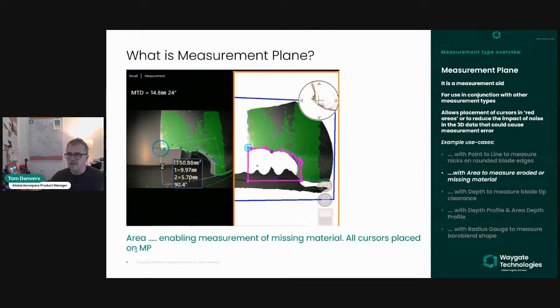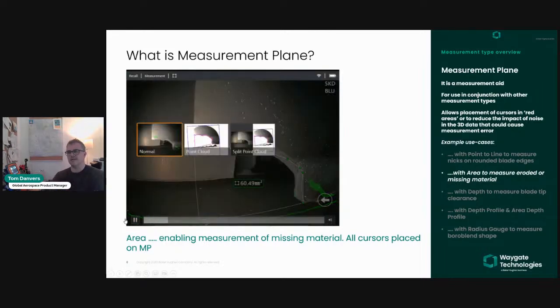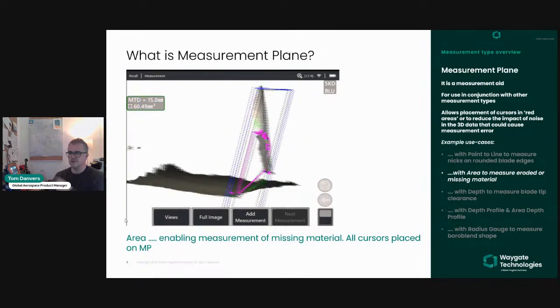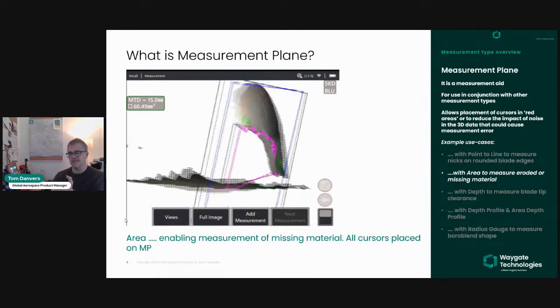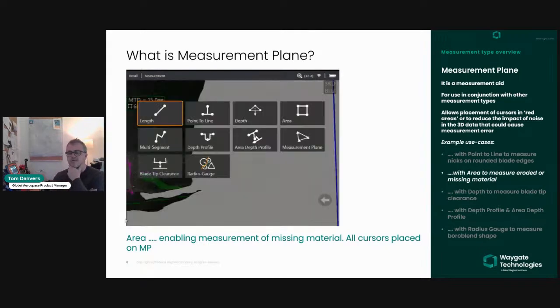I can't remember what the value was. So that's now 50.8 millimeters. And originally it was 60 millimeters. So it's dropped from 60 to 50 millimeters essentially, by making sure you check the point cloud, where you can see here that it's clearly off the surface or off the correct plane of the aerofoil, especially with that point that's dropped onto the abradable liner.